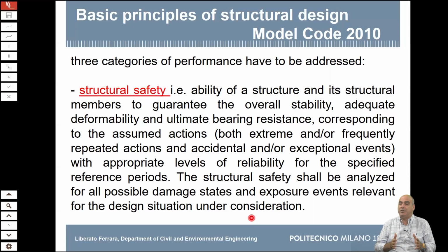Probably there is no person in danger there, except if that water is some contaminated water. If it leaks through, it goes into the water table and there's issues there. Or if you have a container for nuclear waste, if it cracks, radioactivity can come out. That is an ultimate limit state. So the same situation, depending on the structure that you are dealing with, can be at the same time a serviceability or an ultimate limit state. And the issue is that we design for serviceability and for safety with two different levels of reliability.